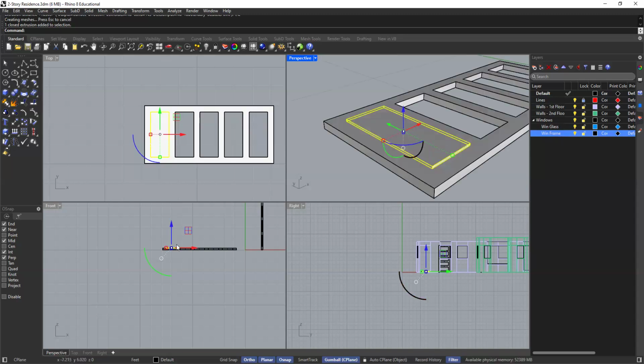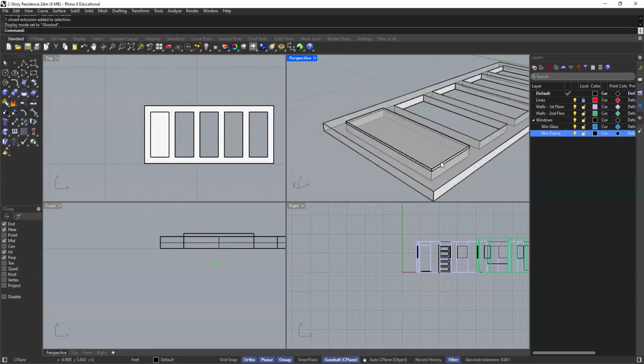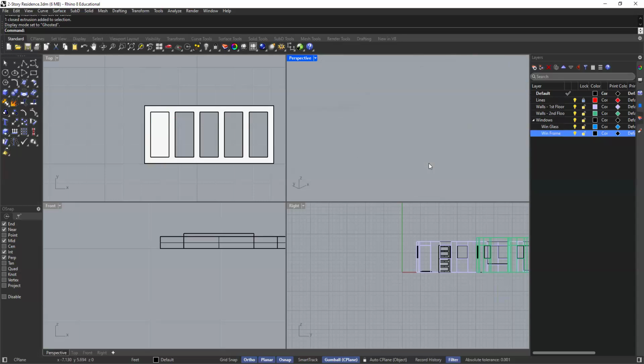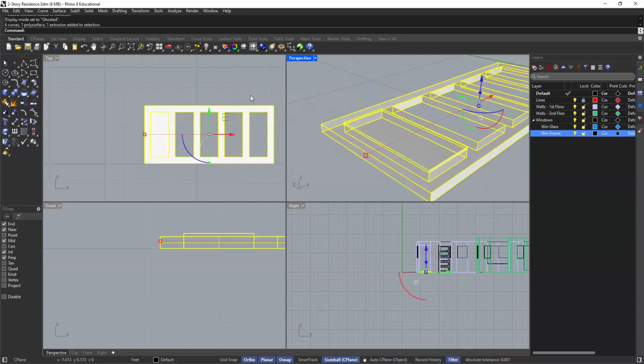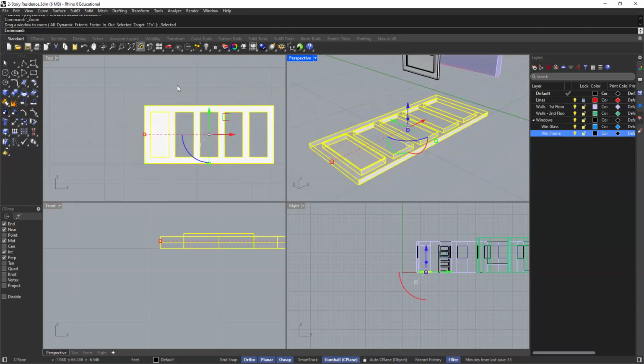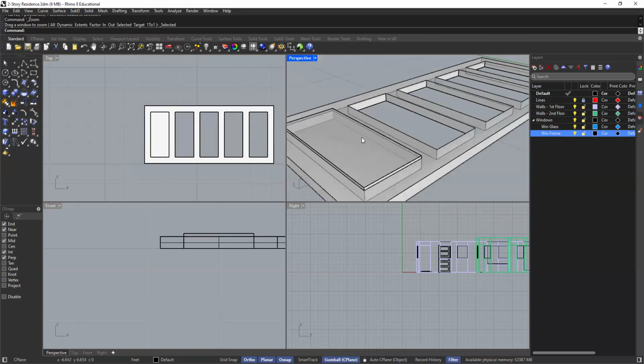Okay. We'll select this massing here. Actually, you know what? Let's go into ghosted view. Notice how when I just zoom in once, it zooms way in, and now I've lost it. So I have to zoom back out, but I still need to get closer. So again, using our zoom selection tool, I'm going to just select the object and then click this, and that's going to reorient the camera around this object. And so now I should be able to zoom in a lot more.